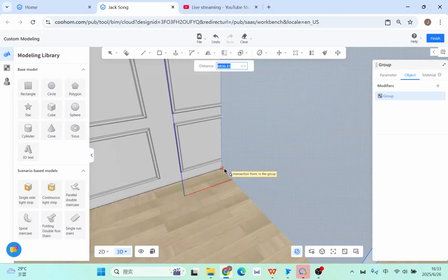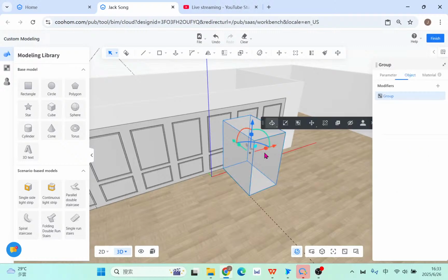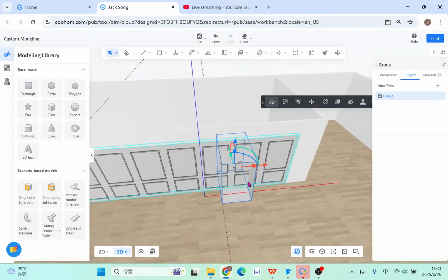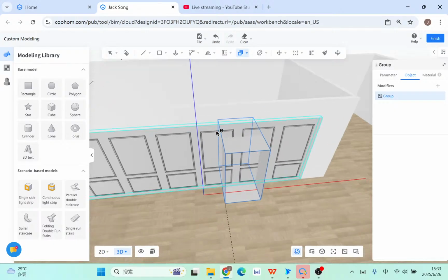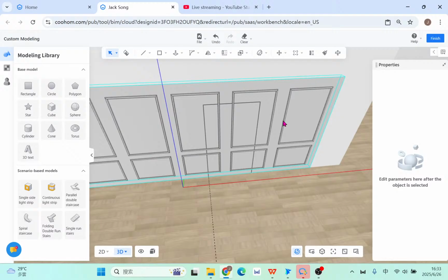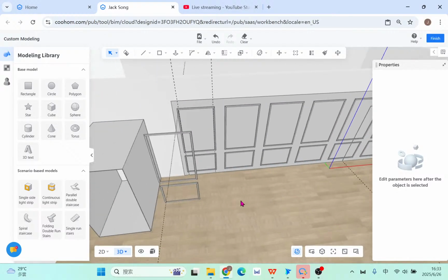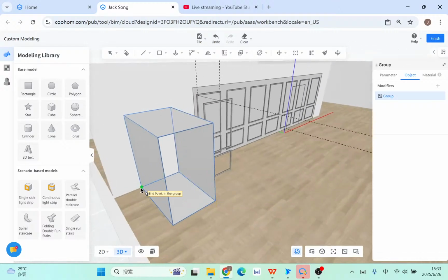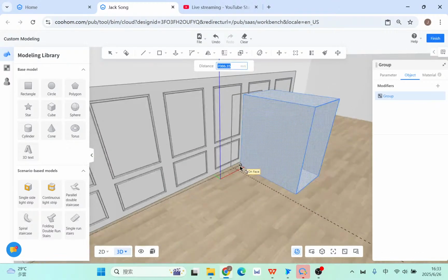Auto snap to the intersection point, and move forward to cut. The first cutting using the subtract here, subtract to delete the back. Now actually we separate them, okay, separate from the walls to the door opening holes, and still continually again click, duplicate, a point to the point.